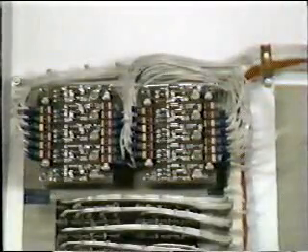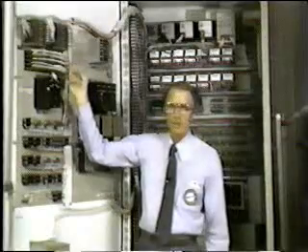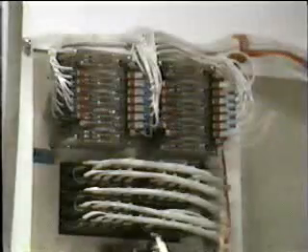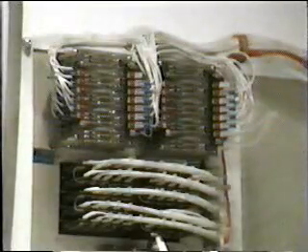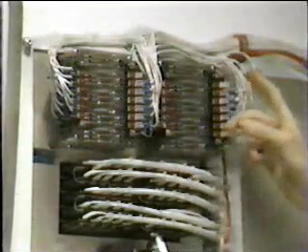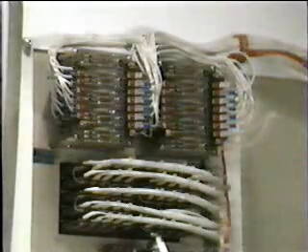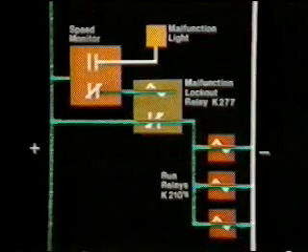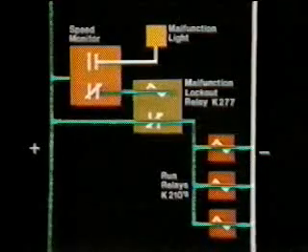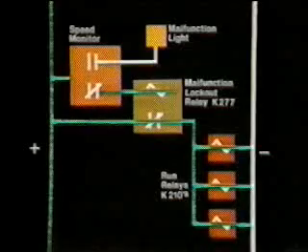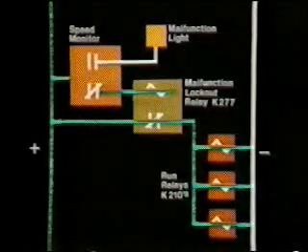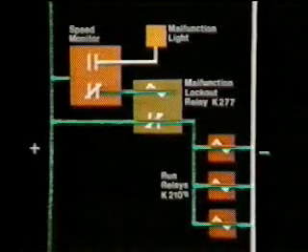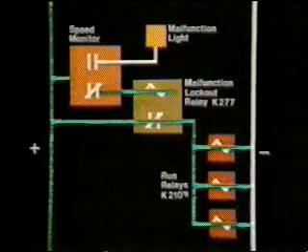Each malfunction control, Z189, is in fact a printed circuit board with 5 separate circuits. The malfunction board has 5 switches leading to 5 separate malfunction lights. During normal engine operation, the protective monitoring device completes a circuit to a malfunction lockout relay to keep it energized. If a malfunction condition develops, the monitoring device will transfer contacts, causing the malfunction lockout relay to de-energize.